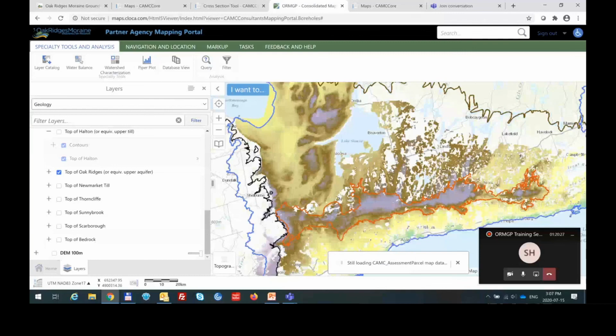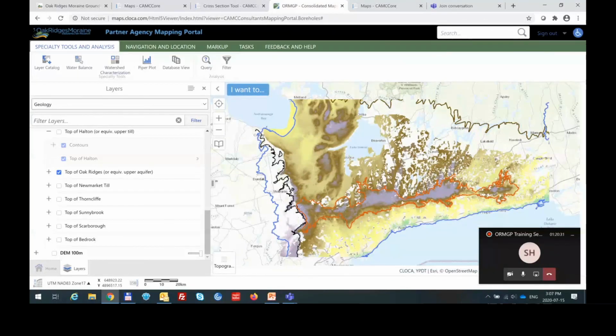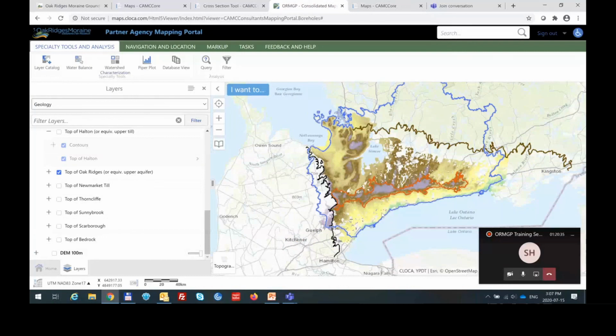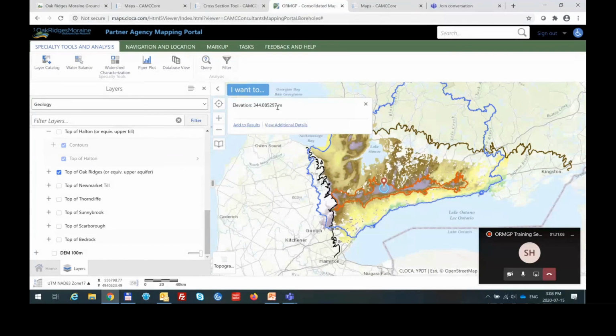Yeah, this is the top of, and you will notice, and this is part of that simplification of surfaces that we're posting, where we have, particularly along the south slope, and it came about from a lot of landfill investigations I've done over the years, and in the Pickering area, and 407 exposed it. We're seeing sands between tills along the south slope. So obviously the moraine is thickest over the mound, the elevation's 344 over the upland areas.